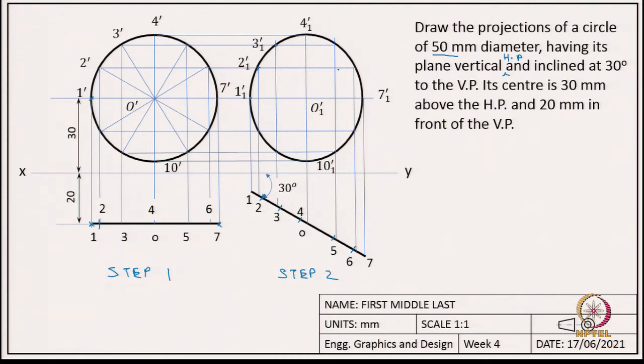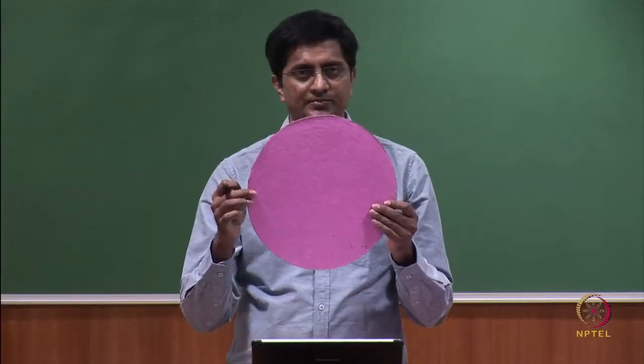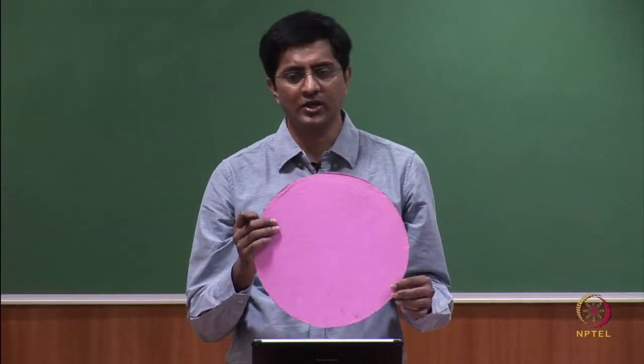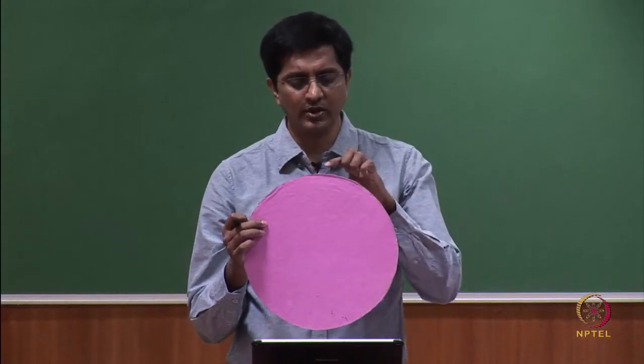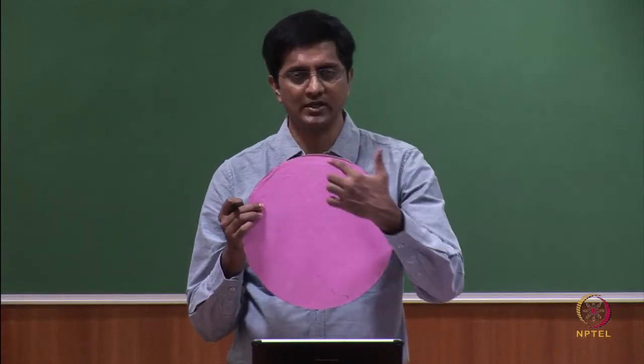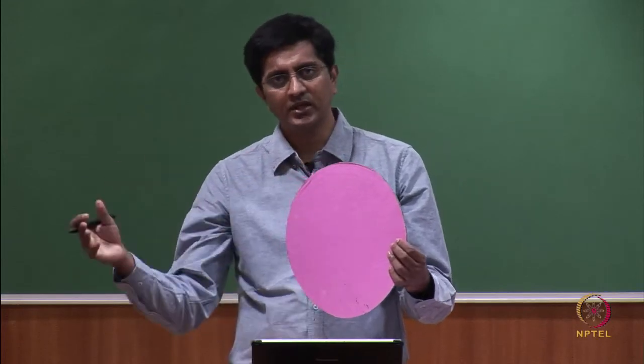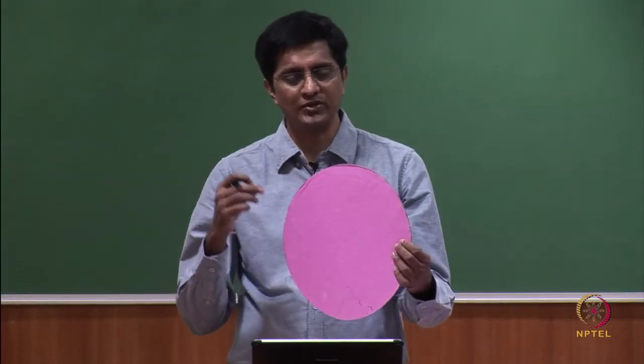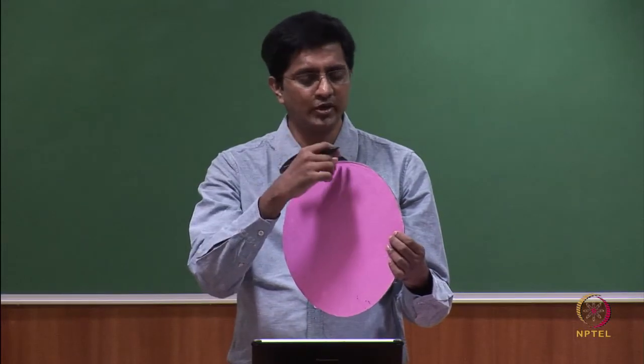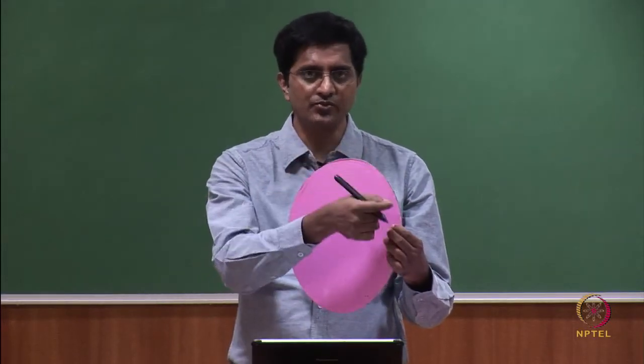So, what we have shown in this slide is how to draw an ellipse when we know the angle by which we rotated this circle. To put it simply, we are just placing 12 points on this circle and then tracing those 12 points in the upcoming projections. So, once we know the 12 points, now we are joining these adjacent points with freehand curves.